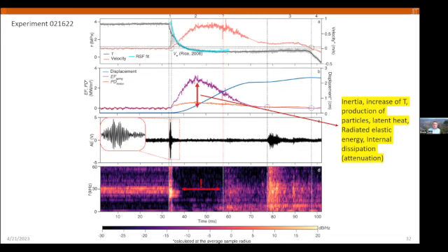We can see clearly that there is a gap of acoustic emission after the acceleration, the nucleation of the event, and this gap here, I'm talking about this. And then we see that the acoustic emission eventually comes back after a while when the sample is decelerating. And decelerating here. So the velocity is 0, then it goes up, then it stays up for a while, and then as it starts decreasing, then you do have a new boom of acoustic emission.